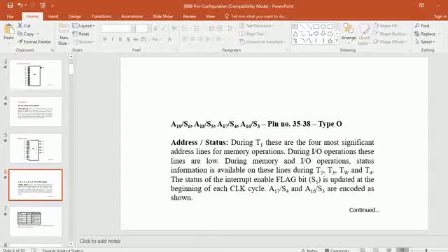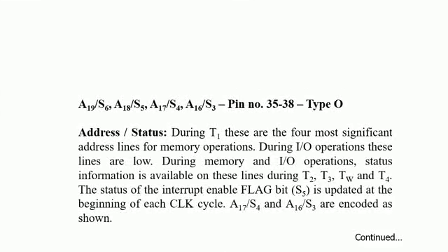In the last class we went through one diagram. Most of the time, the microprocessor is the one which has control over the system bus. But when you are supposed to exchange a bulk amount of data between devices, we do not allow the microprocessor to perform that data transfer, because of the restriction of the data bus. If we allow the microprocessor to exchange a bulk amount of data, it is going to take more time to transfer or receive the data.